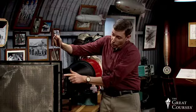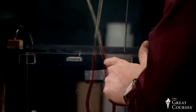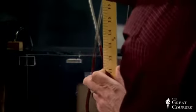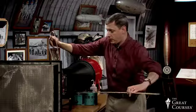So you can see the total pressure is higher, and that's making this side of the water level go down. The static pressure is lower, so this water goes up. It's like a suction, a relative suction. I can measure the change in height, and it's 1 inch.